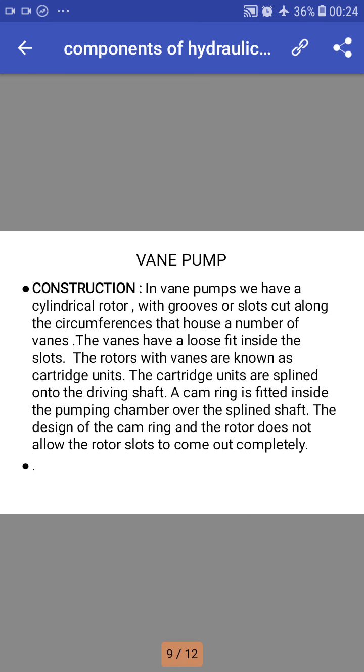Next, come to the second pump, that is the vane pump. In the vane pump, we have a cylindrical rotor with grooves or slots cut along the circumference, housing a number of vanes. Just like in a library, where we put the books in vertically, there are slots on the periphery of the rotor. The vanes have a loose fit inside the slot.